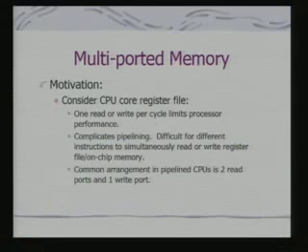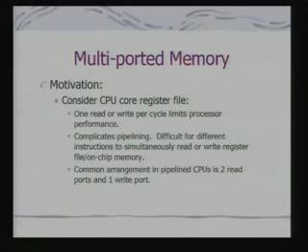Next thing that we have seen is that in many embedded processors, in DSP processors as well, there are multi-ported memories. The obvious motivation is that in any kind of pipelined processor, which today we find in many of these SoCs and embedded systems, if I have one read or write per cycle, it can limit the processor's performance.